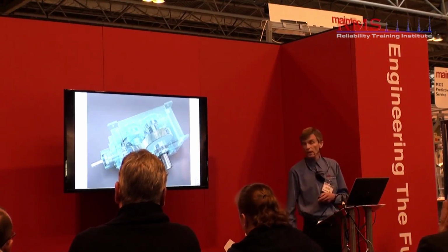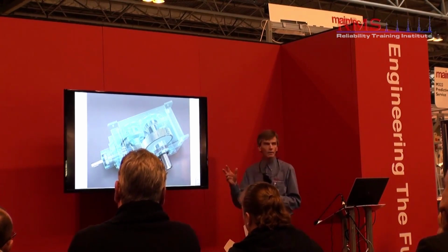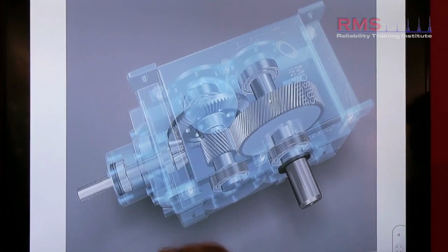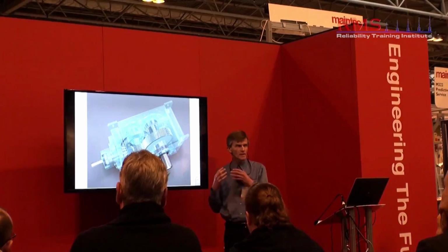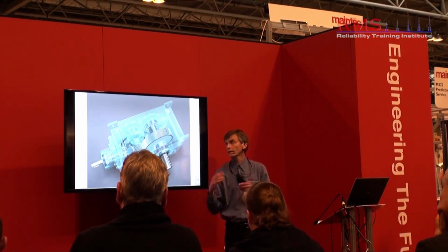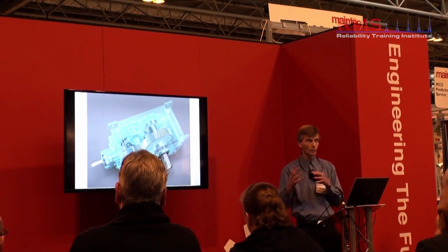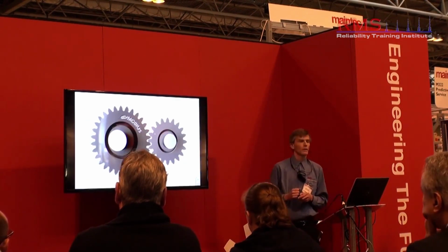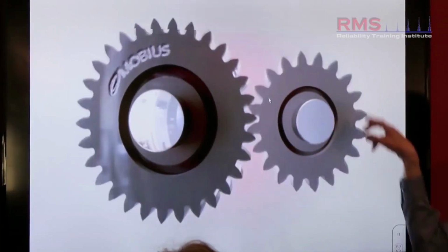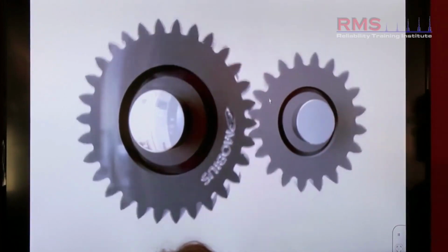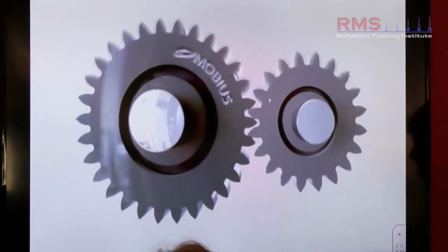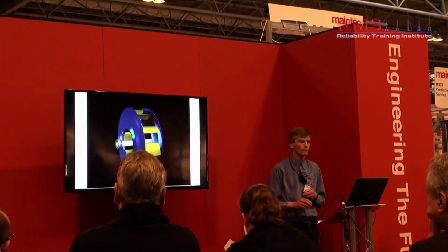Obviously much more detailed here maybe, but in simple terms, each gear will have a certain number of teeth. And this defect on one of the teeth, or all of the teeth, or some of the teeth, the heartbeat pattern will be distinctly different, again, to what we saw before, where the machine was misaligned, or secondly, what we saw with the volutes or the blades on the pump. So you can see there, obviously, you've got a certain number of teeth on each gear. That will produce a certain number of pulsations. If there's 20 teeth on this gear, for example, 20 pulsations per rotation. So we can trend, we can track that particular heartbeat and measure the health.